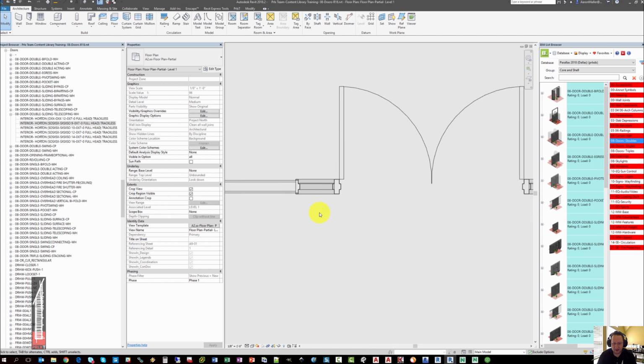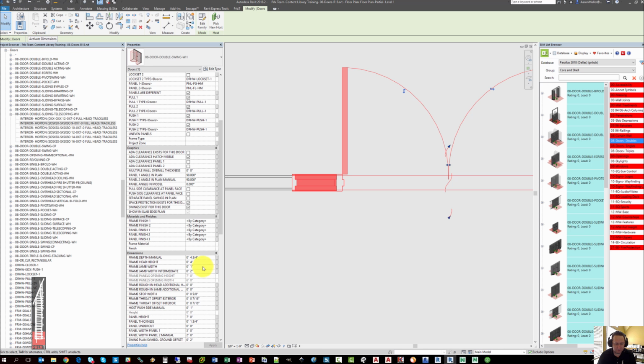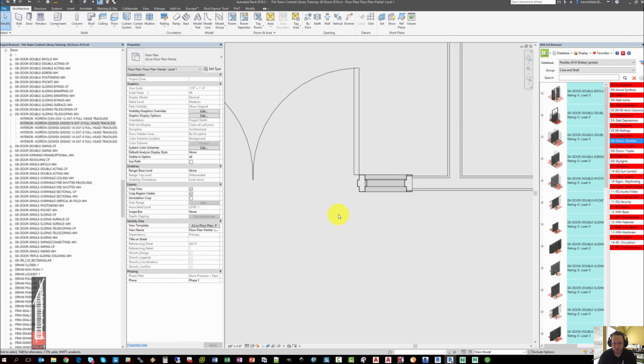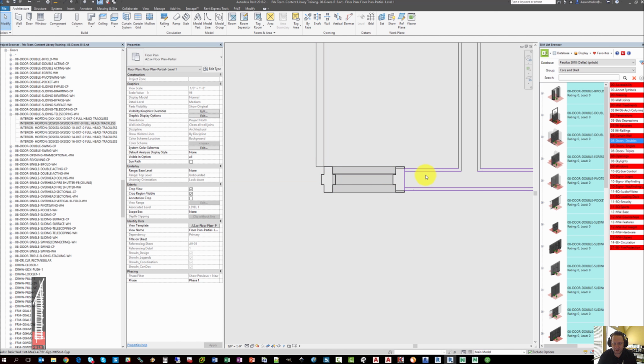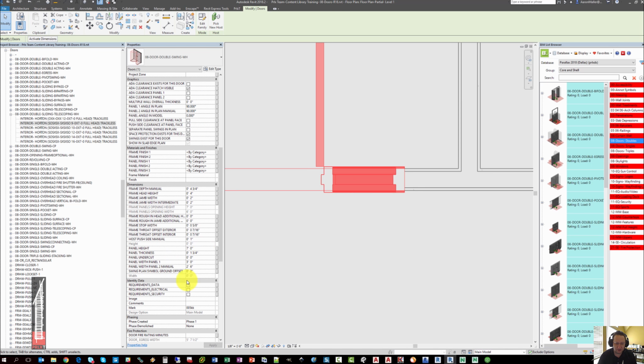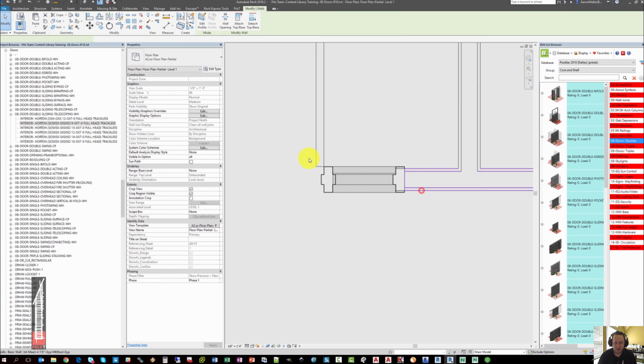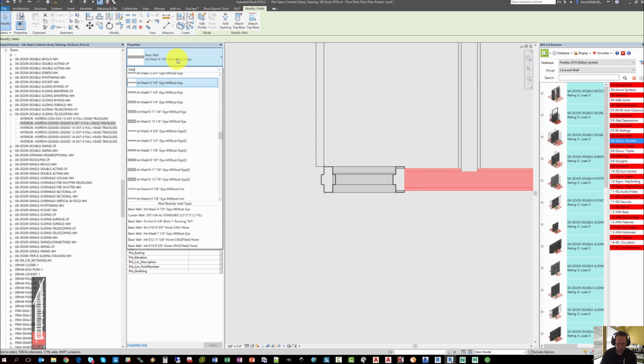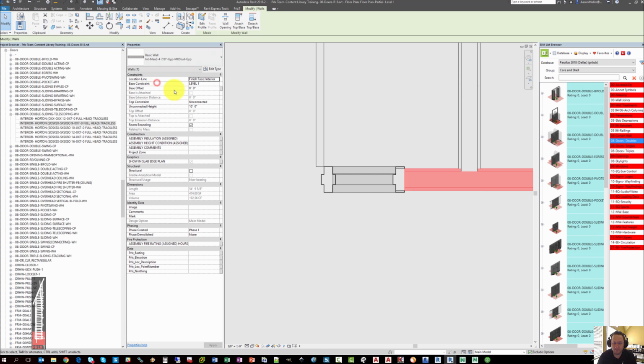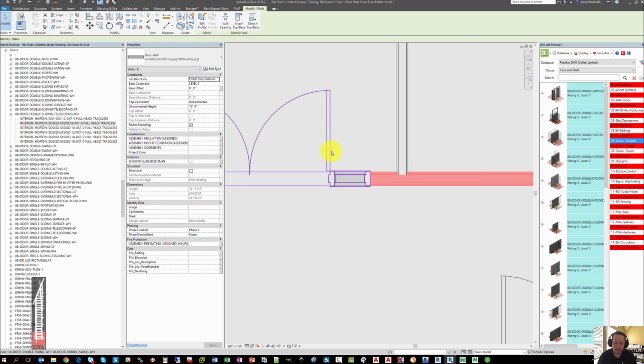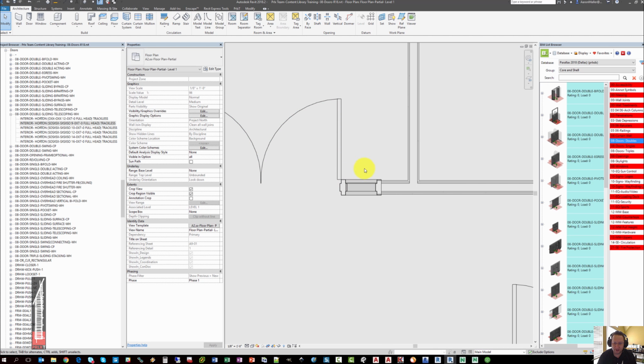Now, on the interior door, if we leave the frame at 2 inches, in this case, we want our interior frames to inherit the size of the wall plus a normal dimension, which is standardized in the door frames or in the doors as 7/16 inch. This means that if this wall changes to a thicker wall, the door frame will grow with it. The door schedule is also reporting the depth of this frame so that that can be coordinated against your door submittals at a later date.